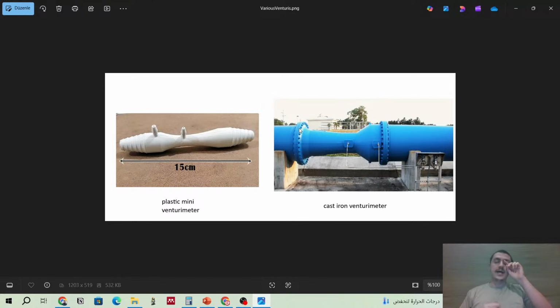So in a lot of applications, you need to measure the flow, and there are several ways to do that, but Venturimeter is one of the simple ideas how to measure the pressure, how to measure the mass flow rate depending on the pressure drop between these channels. When you decrease the channel diameter, you increase the velocity, and there will be a pressure change, okay? Depending on the pressure drop, you evaluate the mass flow rate. Okay, it is basic Bernoulli principle. Maybe you remember it from the bachelor's.